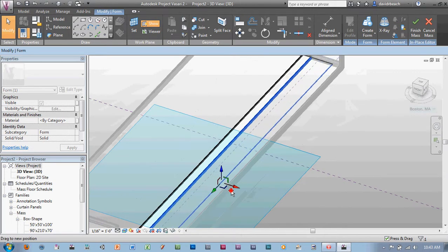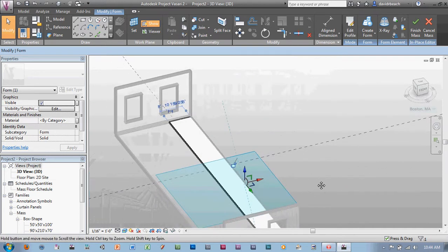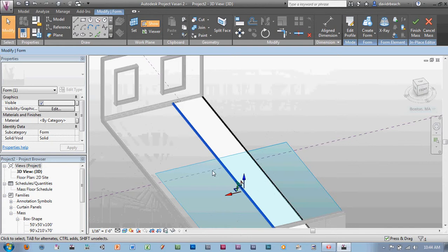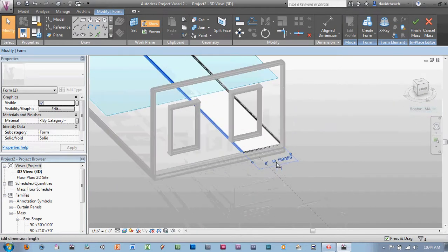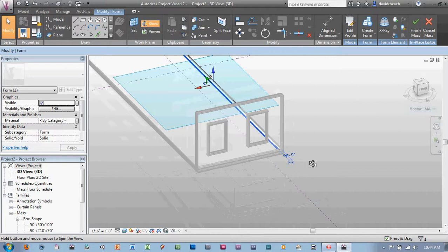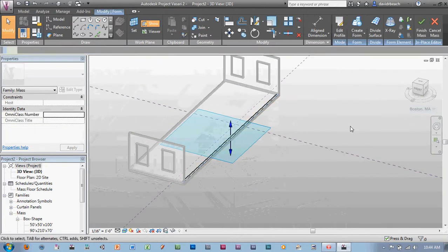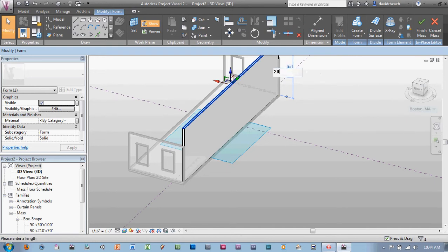The free movement comes from when you select inside of the widget one of those surfaces, and there's a free move that you enter into. And again, I want to make this wall, rather than sliding that in, I'm just going to select here and say I want that wall to be 1 foot thick. Select everything, Create Form, and again our walls are 20 feet tall.